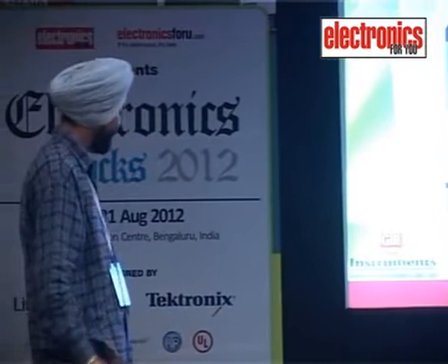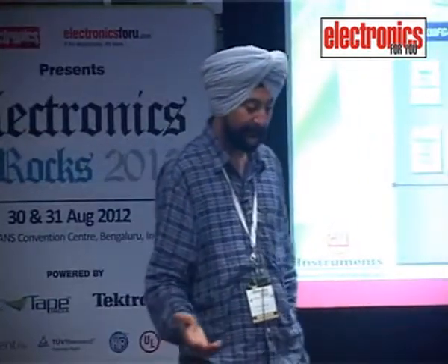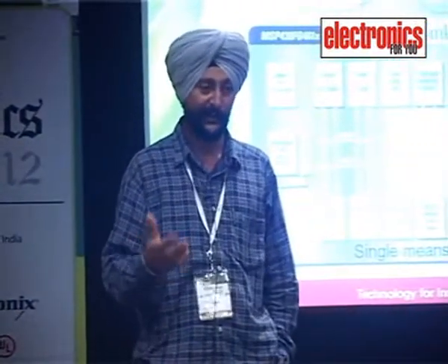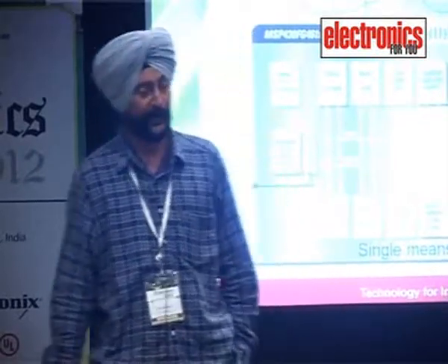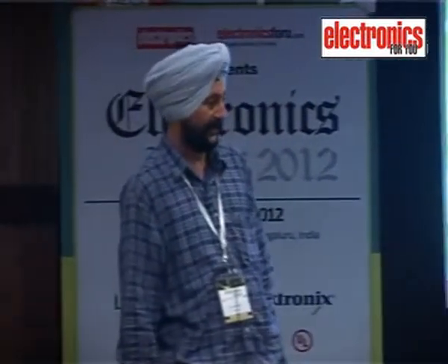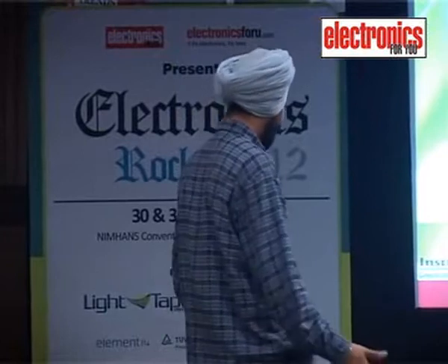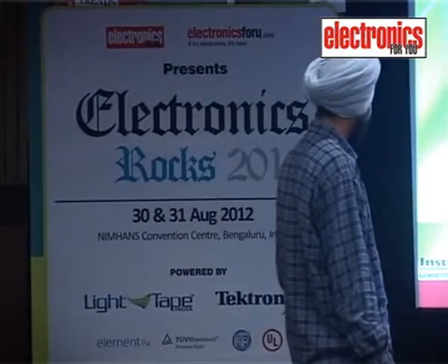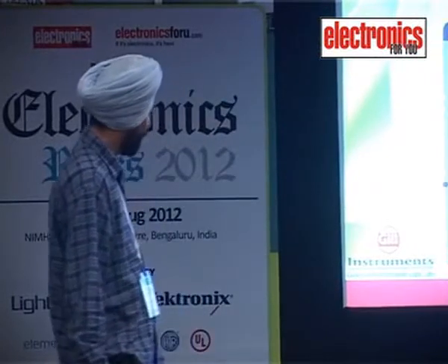Then we have built-in LCD drivers, because when we talk about MSP 430, you can find a lot of MSP 430s. It goes into the handheld instruments, healthcare instruments. So that's where we need some kind of a user interface. So we have a built-in LCD driver. So you need not to use any special LCD module which will consume more power. So we will be having a family with built-in LCD drivers, basic RTC built-in. As I said, we have a 2-channel DAC.